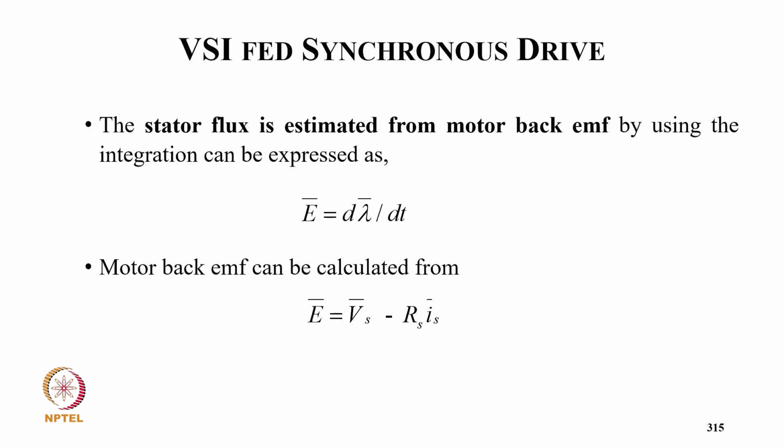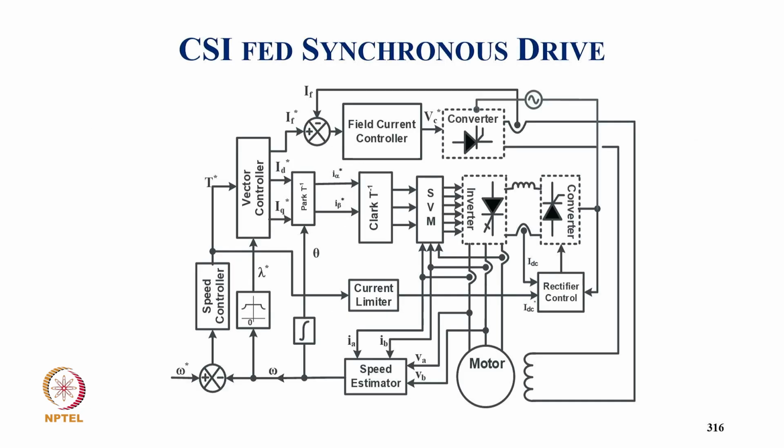motor back EMF by using the integration, which can be expressed as lambda equal to integral of E dt, and motor back EMF can be written as Vs minus RS IS. And this is typically the current source inverter fed vector control of a synchronous motor type.